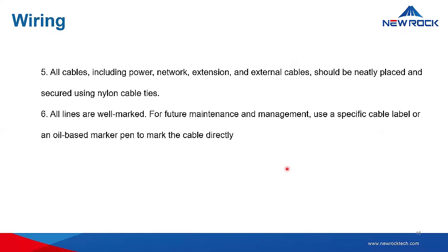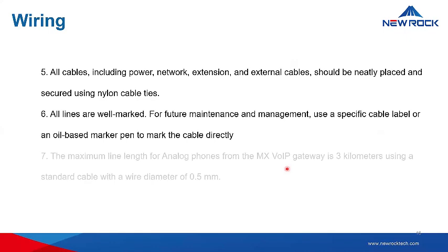So you don't have to unplug and plug in because you don't know, as there is no marking. So as much as possible, you need to mark the cables using an oil-based marker, so that the marking is neater and directly on the cable.